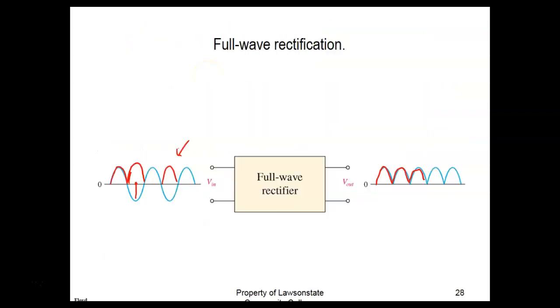But when we get over here, for every cycle on our input, we get 2 cycles. So this is a repetition on an output. So on a full wave, your output pulse frequency is going to be my frequency N times 2. And that becomes a big feature when we start trying to filter this, and we'll look at that when we get into filters and try to turn this into a DC instead of pulsating DC.